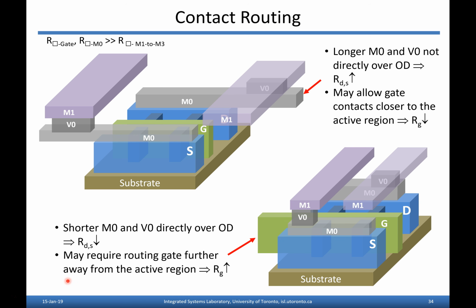And that's why, you might say, why aren't all these parasitics, especially for the low layers of metal, included in the device models to begin with? Because obviously you have to contact the device somehow. Well, there are different layout styles you could take that might change that trade-off. So these parasitics are not usually included right in the base device model. And as a result, you can get a big surprise after you do layout.